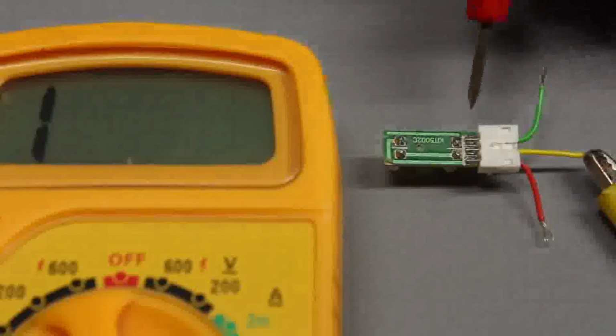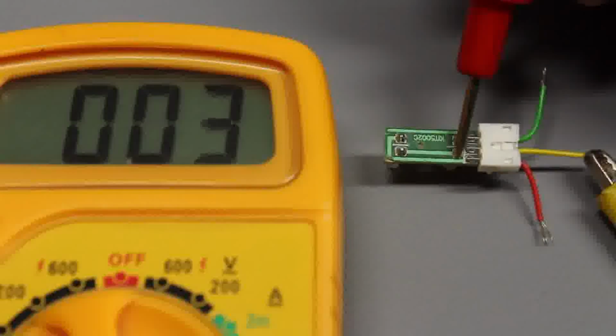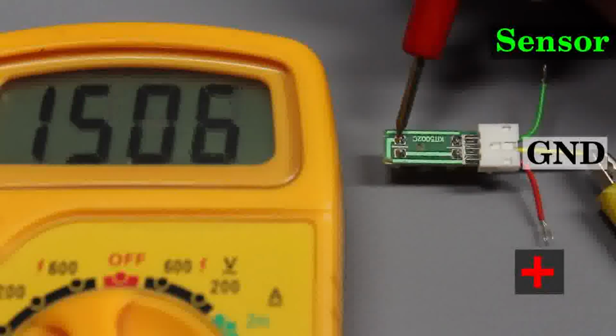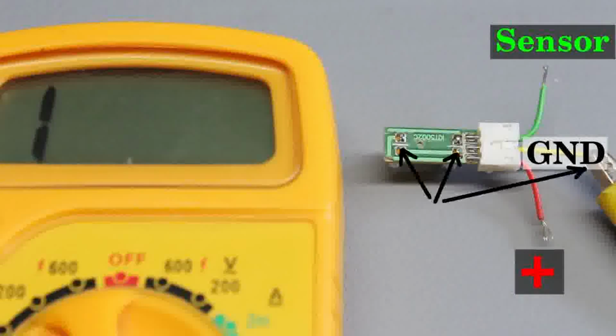If that path is hidden, you can dial your multimeter to continuity measurement to determine what pin of the LED and receiver side are joined. The third terminal is joined with the second pin of the receiver side. The polarity of the receiver side is obvious, as demonstrated the joined pins are connected to ground.